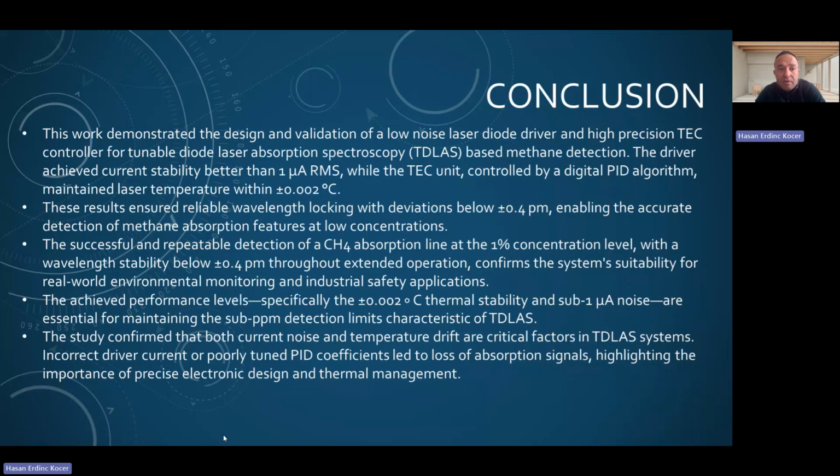features at low concentrations. The successful and repeatable detection of the methane absorption line at 1% concentration level with a wavelength stability below minus and plus 0.4 pm throughout extended operations, and the achieved performance levels, specifically 0.002 centigrade degrees thermal stability and also sub 1 microampere noise, are essential for maintaining the sub ppm detection limit characteristics of TDLAS.